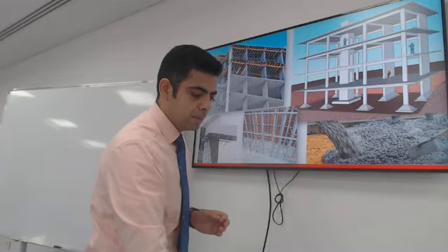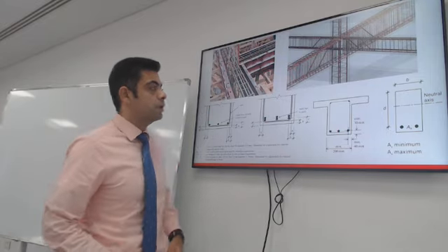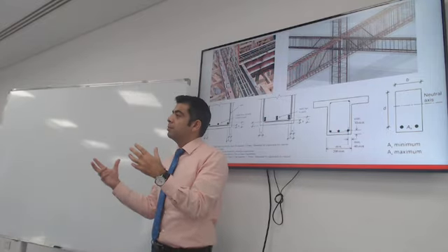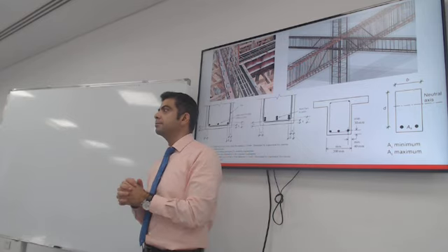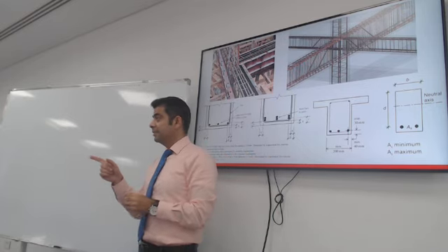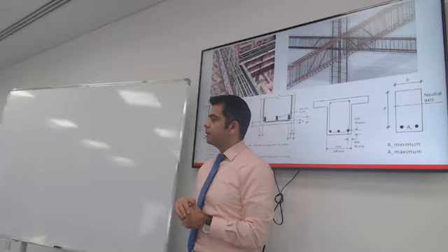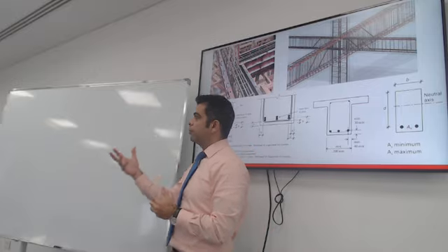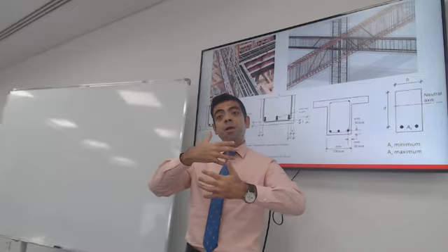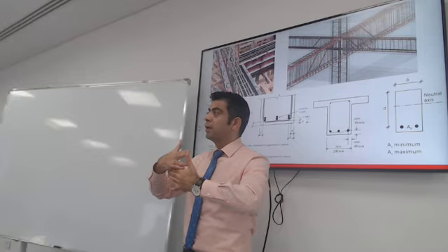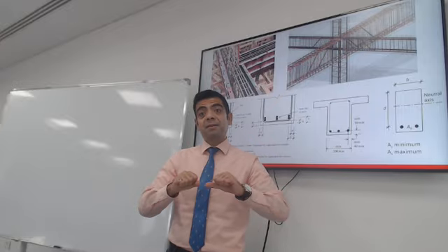So any guess why do we need minimum reinforcement? Why does reinforced concrete behave differently than just pure concrete? Carry tension. What's that? That steel bars carry tension inside the beam. I like that very much. Yes, that's true. Reinforced concrete, or concrete and steel, they will complement each other in a very important way. Tensile stresses are best suited to be resisted by steel.